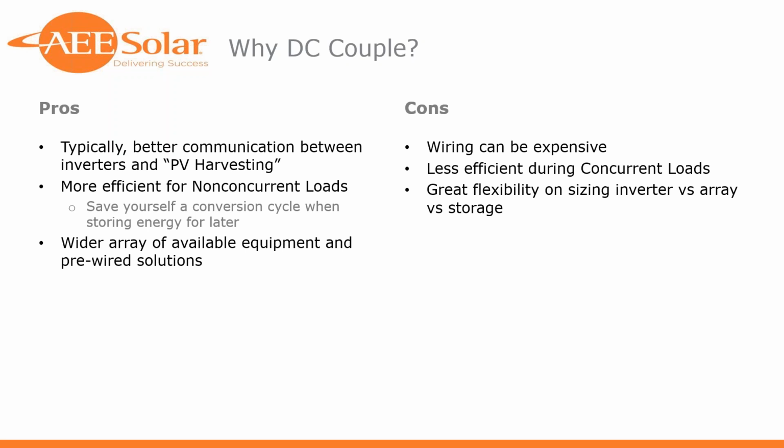Obviously because of the length, and then just because of the voltage at which the connection between, call it, the PV and the battery inverter is happening. So if you're in a DC coupled system, you're running cabling between that charge controller and that inverter at a 48 volt level. Ohm's law being what it is, the conductors you're going to need to size for, call it, 6,000 watts at 48 volt are going to be a lot thicker, a lot more expensive than they would be in an AC coupled system, and we'll get into that in a second.